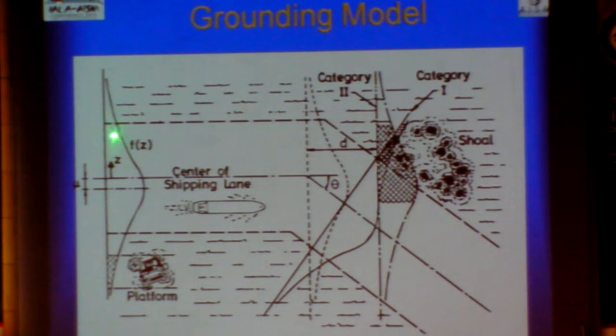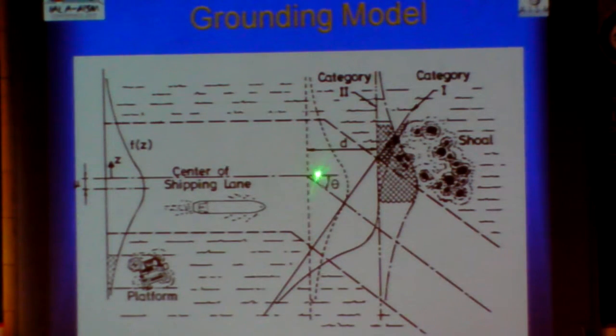So there's a certain probability that a ship is here. There's some higher probability that the ship is located here, laterally on the lake. Then the ship is supposed to turn here, and at this moment here, we have this obstacle, and if you project the obstacle onto this distribution curve that we have from here, we will have an area, and the fraction of this area compared to the whole area under the curve is the fraction that we use to figure out the number of candidates.